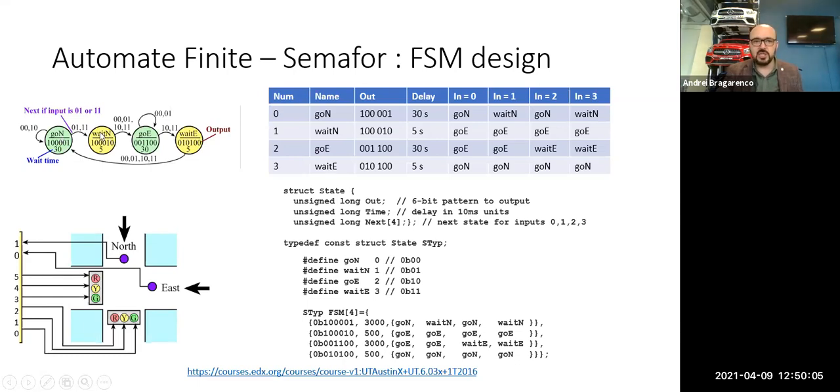Now, the transition, the yellow transition, yellow for the north, meaning stop driving, preparing for the change to green on east. What will we do? We'll switch on the second bit, the yellow for the north, and we'll still keep the red on the 5th bit, red for the east.